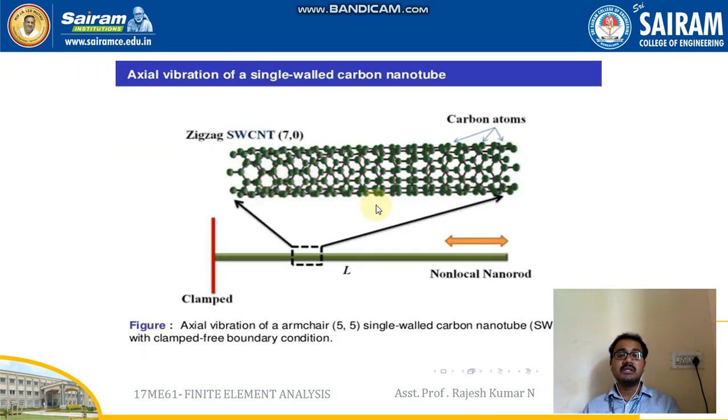We have some examples in our laboratory where we will be discussing modal analysis and harmonic analysis. In the modal analysis, again a cantilever beam will be taken, but instead of this kind of loading condition we will be considering a point load acting in the y direction. The direction can be plus or minus, but we will be applying it in the y direction only, and accordingly we will find the mode shapes, and we will keep changing the magnitude of the load applied. If you keep changing it, there will be a change of the frequency, and that comparison will also be shown.